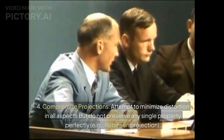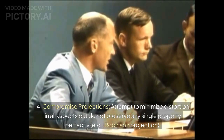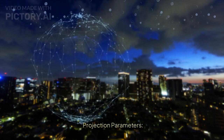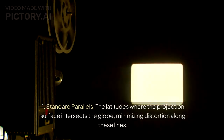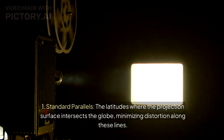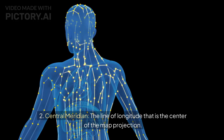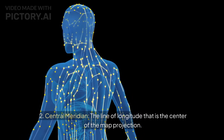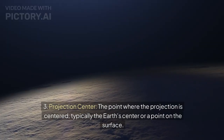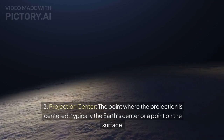4. Compromise projections. Attempt to minimize distortion in all aspects but do not preserve any single property perfectly, e.g., Robinson projection. Projection parameters. 1. Standard parallels. The latitudes where the projection surface intersects the globe, minimizing distortion along these lines. 2. Central meridian. The line of longitude that is the center of the map projection. 3. Projection center. The point where the projection is centered, typically the Earth's center or a point on the surface.